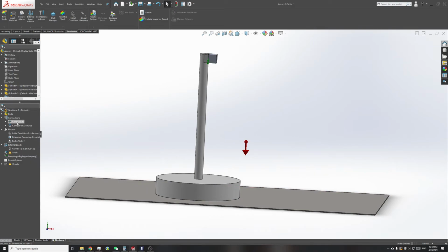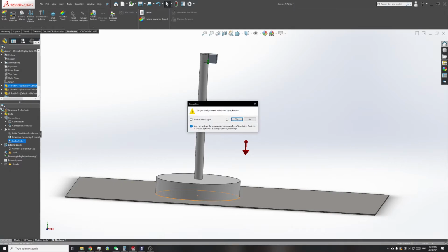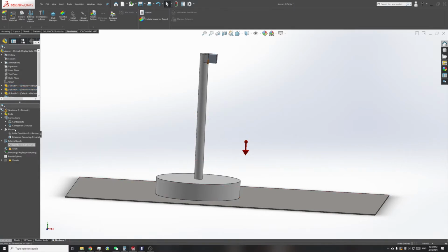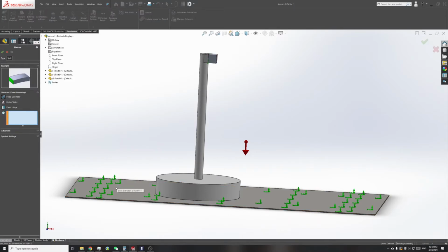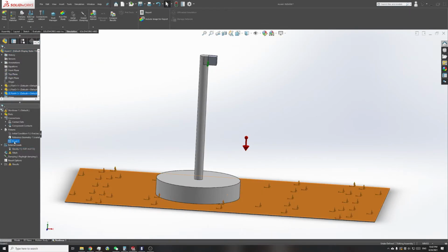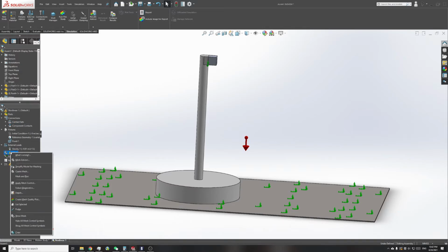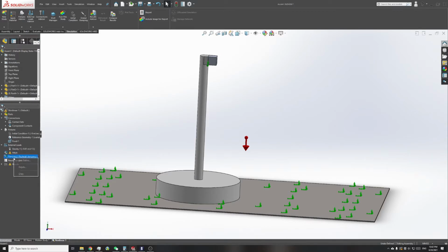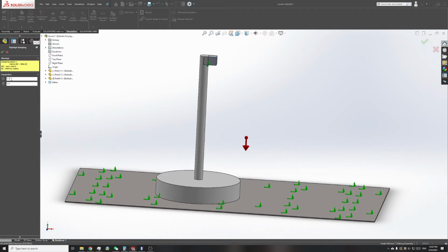Right, so right now we have some new constraint. I need to remove roller, to add a fixed geometry. So we fix the ground. Yeah, I hope that will work. The mesh shows an angle because we changed it, so you need to mesh it. But if you click wrong, it will mesh it anyway. Oh, damping, yeah. You can have some damping. You can put a number here.